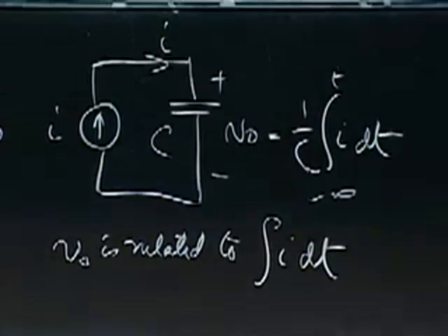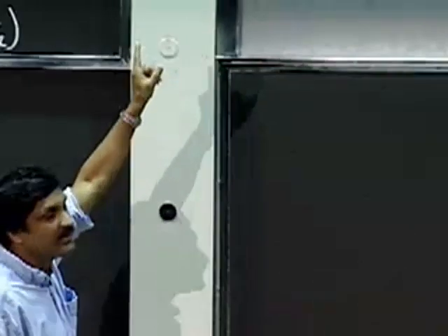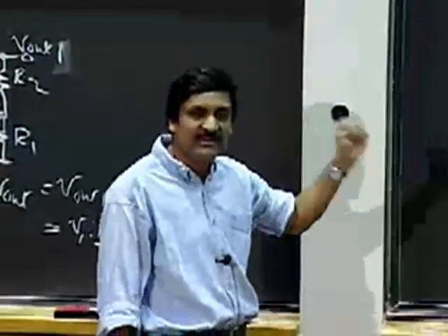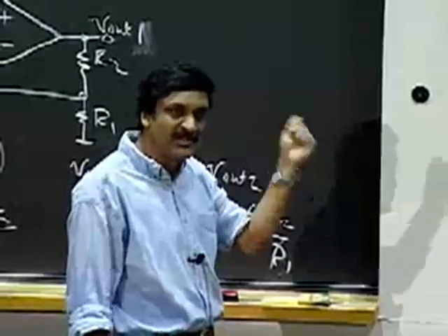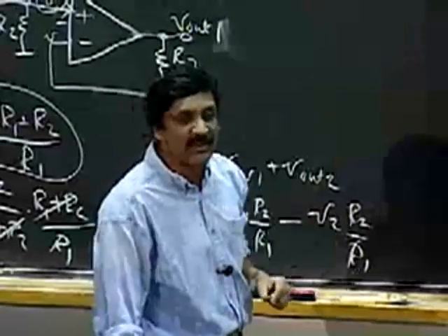Okay, that's interesting. So I've got an integral in there, but I have a current. Notice my goal was to integrate a voltage. What I figured out how to do is if I can turn that voltage into a proportional current, and then pump that current through a capacitor, I'll get the integration that I want.